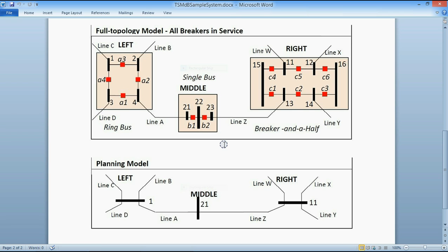but you would do the data entry in sort of a hybrid scheme, whereby, for example, you might put a branch in for each leg of a ring bus, and then the branch for the line would not have a breaker at this end, but would have a breaker at this end. Of course, the rating information for this end, there would be terminal information at this end of the line, because you've got relays that trip that line.